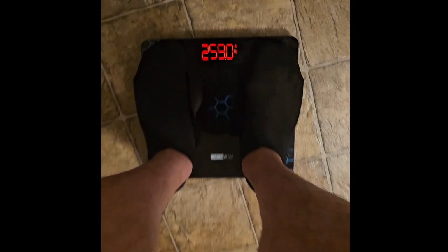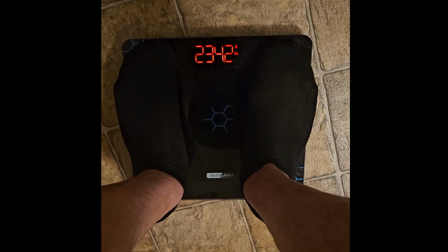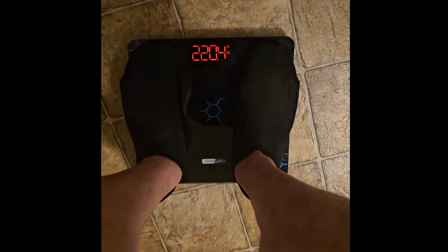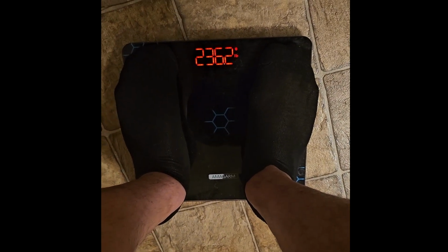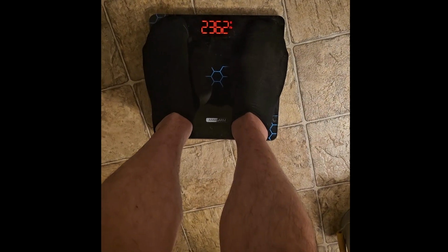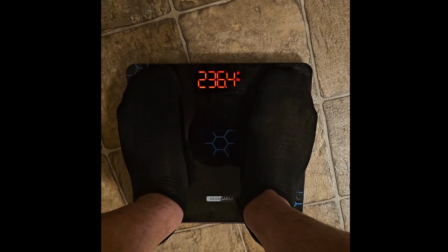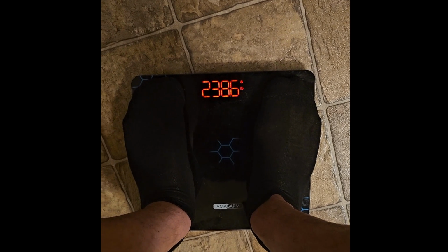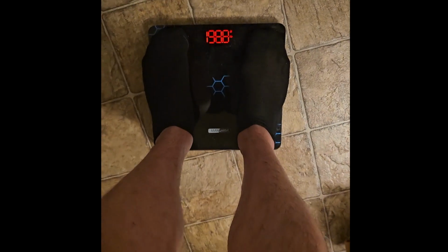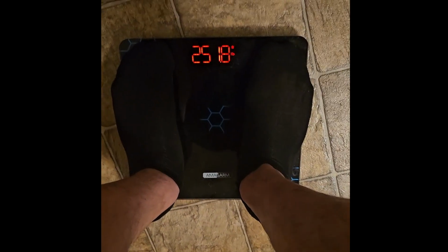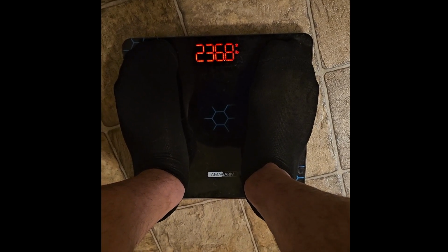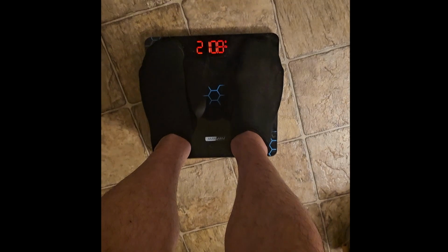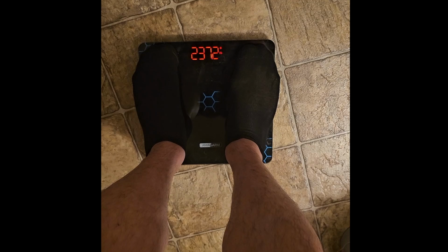To help better explain this, I did a simple demonstration using a bathroom scale and me. Imagine my feet are the tires and my legs are the suspension links. So I'm starting in a down position, call that the static position. Think of your car fully setting on its springs. Then I push, accelerating upwards, and you see an increase of the weight on the scale. And that's during the acceleration of me moving up.